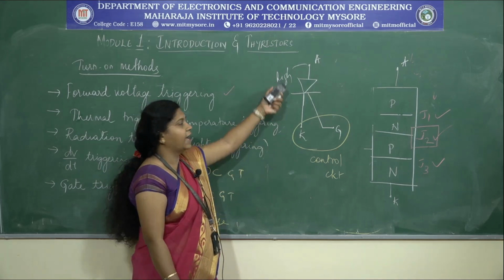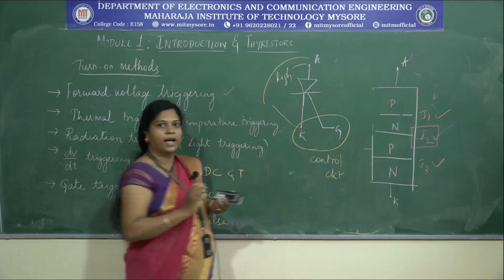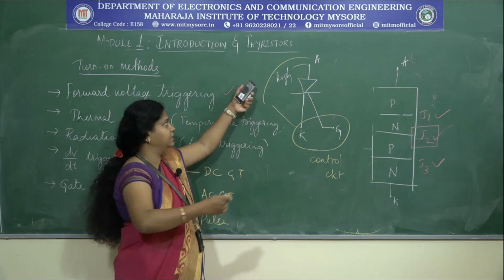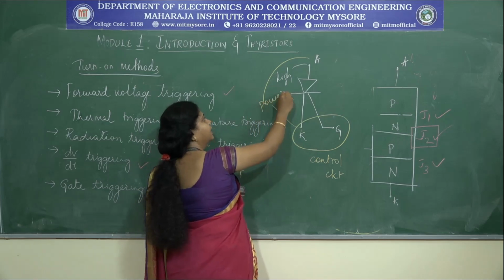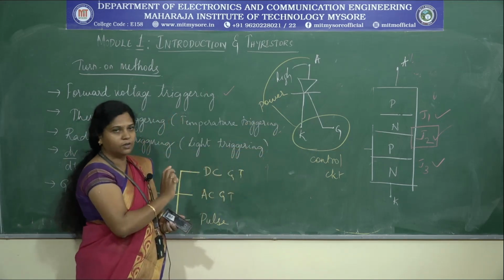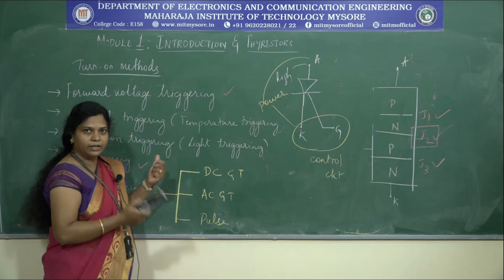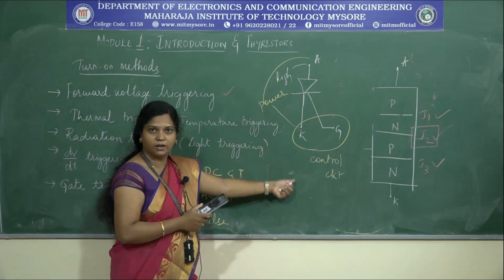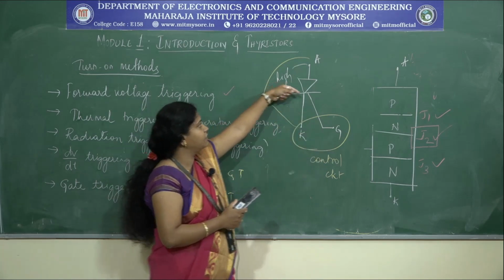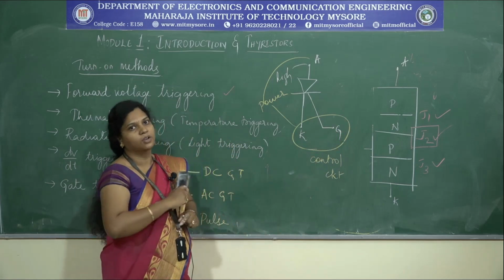Okay. Similarly, anode to cathode, whatever the voltage you are going to apply is always a high voltage, and this part and the other equipment, the load, the motors, whatever the other equipment you are connecting with this will always be of a high power, hence it is known as the power circuit. So this gate to cathode is known as the control circuit, anode to cathode is known as the power circuit. Okay. So what we need to do now? We need to isolate power and control circuit. Why? High power, here all the low power equipment you are using, once if the power flows into the gate, then all the components that are connected in the gate circuit will be damaged.